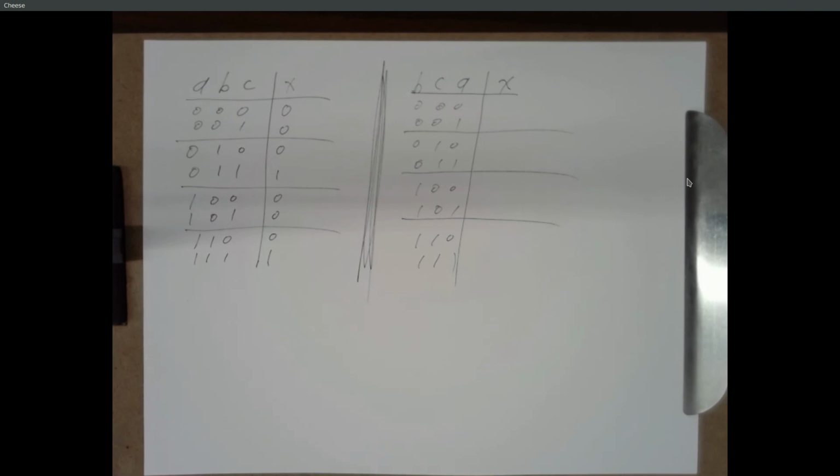And so this truth table is equally valid, because there's nothing that says we have to put the inputs in alphabetical order. We always want to write our truth tables with the input bit pattern counting in binary: 0, 0, 0, 0, 0, 1, 0, 1, 0. We're going to stick to that, because that's pretty much a solid convention, but we don't have to alphabetize the inputs. I think we could do BCA because that's our dog's initials. Perfectly valid.